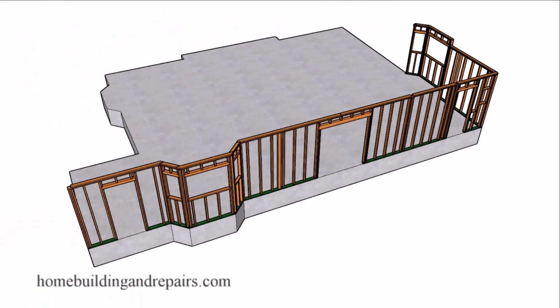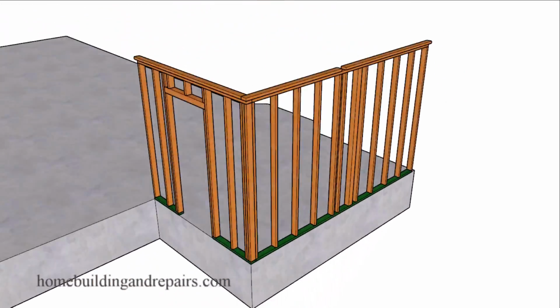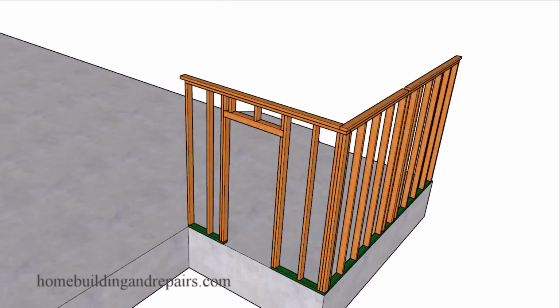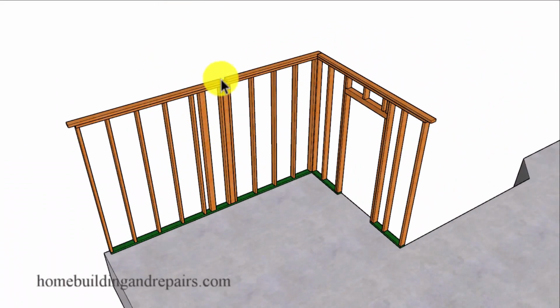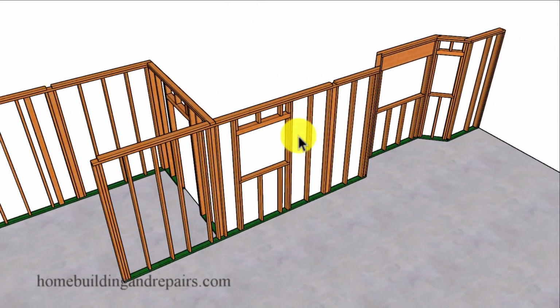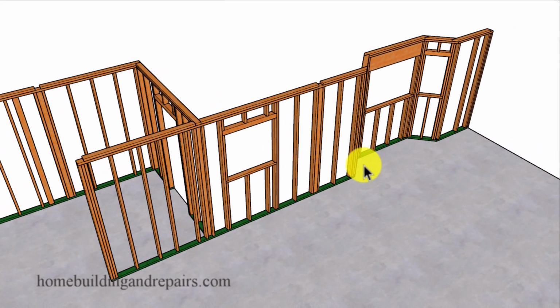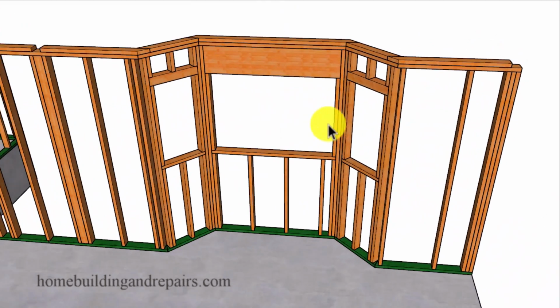Exterior door. Next up, let's continue working our way around the building where we have a couple more walls, along with another support post here and another channel for the interior wall to intersect into, along with another exterior door. And of course, both of these doors will exit onto the exterior deck. And then our next wall, and you can notice here that this one extends beyond the framing of this wall here, exterior here, interior here, to provide us with a nice structural connection here, something that you're always going to be looking for when you're framing walls.